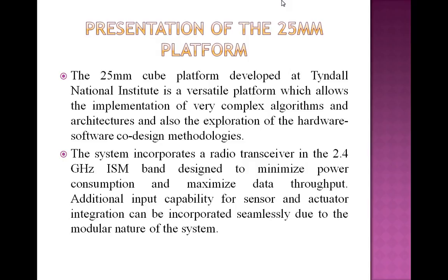This is an 8-bit microcontroller with 128K bytes of in-system programmable flash. The user can easily program the device with custom protocols. The Atmel microcontroller can be programmed to operate in sleep or power down mode, awaiting activity on an interrupt pin.